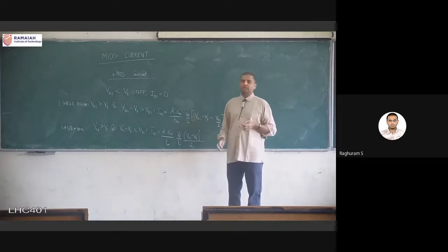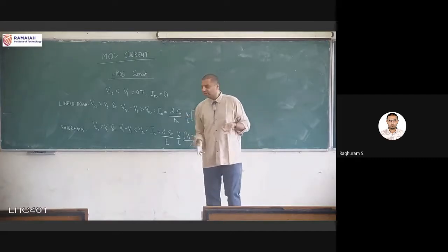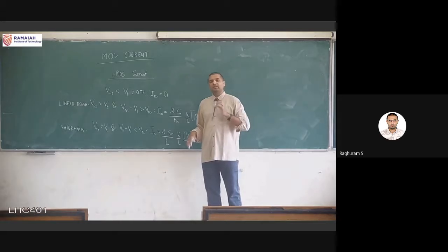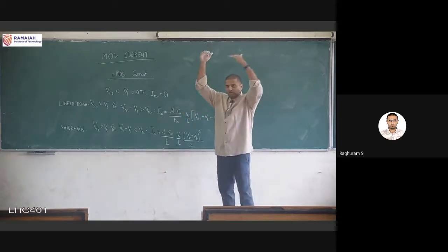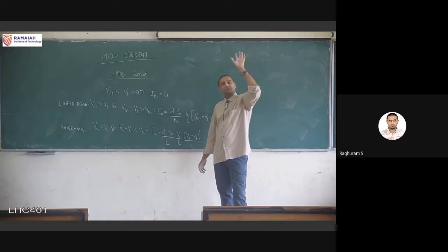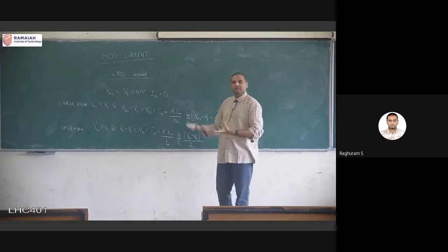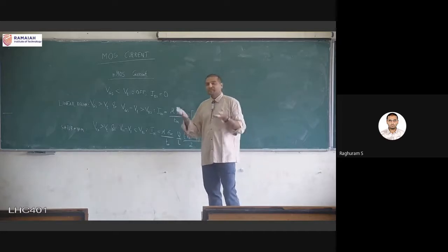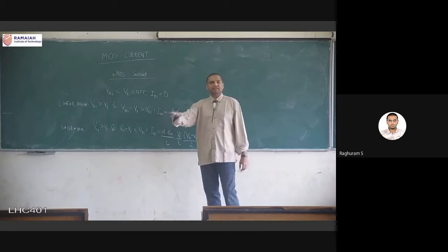T oxide. Now, T oxide, you might think, okay, let's make it a little thicker. Okay, we can change T oxide. But the problem with that is the technology. Whenever you're working in a particular technology node, at the start of the design itself, much before we decide to calculate the current, the technology node will be decided. That is, for this particular design, this is our budget. So based on this budget, to get the best possible performance, we might work at the 65 nanometer technology node. When something like that gets decided, automatically this TOX is also fixed, not possible to change.